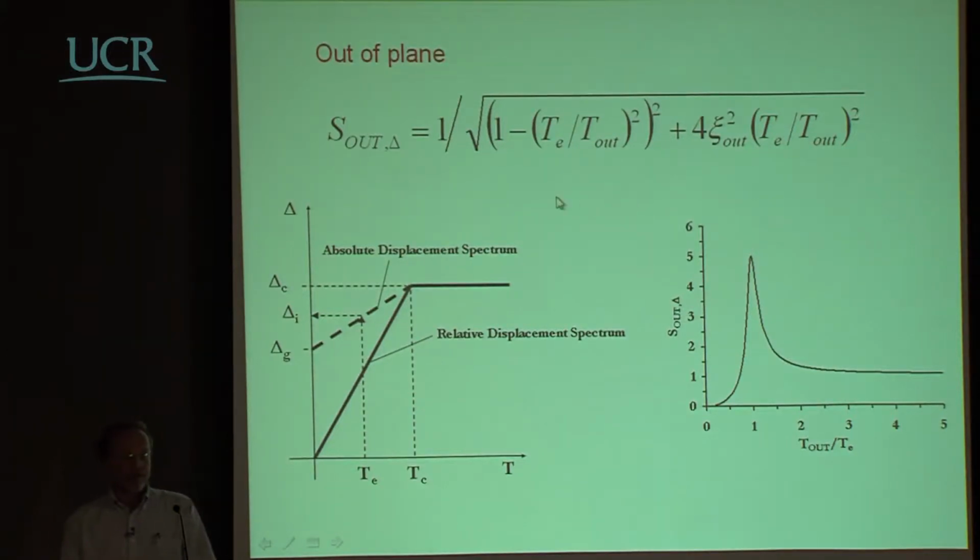The only other thing that we have to take care of is that when we are looking at the base of the structure, at the structure responding to an earthquake, if you have a very stiff structure, the displacement is essentially 0 because you are thinking in terms of a relative displacement. In this case, we want to have the displacement at the floor.